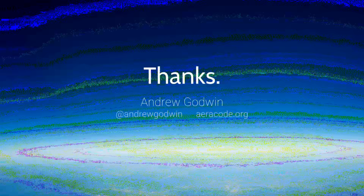Could you make your own LiDAR with an old laser printer mechanism or something like that, for less than 20 grand or something? The laser is not the hard part. It's the receiving of the laser that's the hard part. Shining a laser is very easy. Accurately measuring the time of flight is much harder. There is decent entry-level single laser stuff. It's a case of taking that, mounting it on an accurate gimbal and mapping it. But I'm probably going to get the most basic laser rangefinder I can and try to do a cheap, hacky version of it. I think that's my next project.